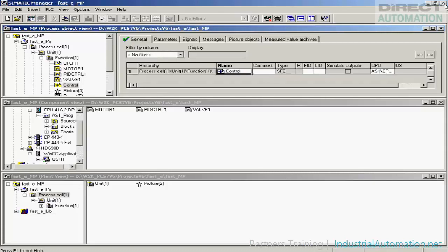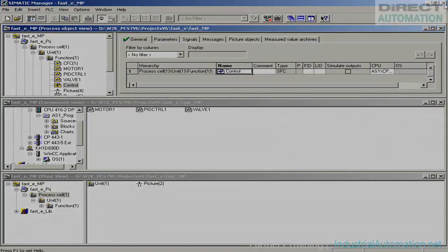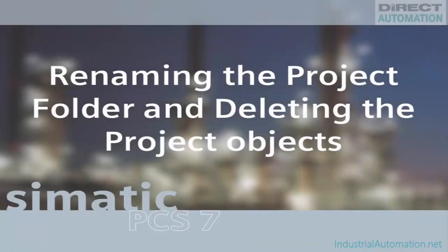The sequence of operations called Control switches the motor 1 on as soon as the process value PV-in goes above 50. After 10 seconds, the motor is switched off again. This is a very simple application to illustrate the power and ease of use of the SFC editor. Real sequential control operations can be far more complex. For example, it is typically recommended to include an evaluation of the feedback signals within the transition conditions.